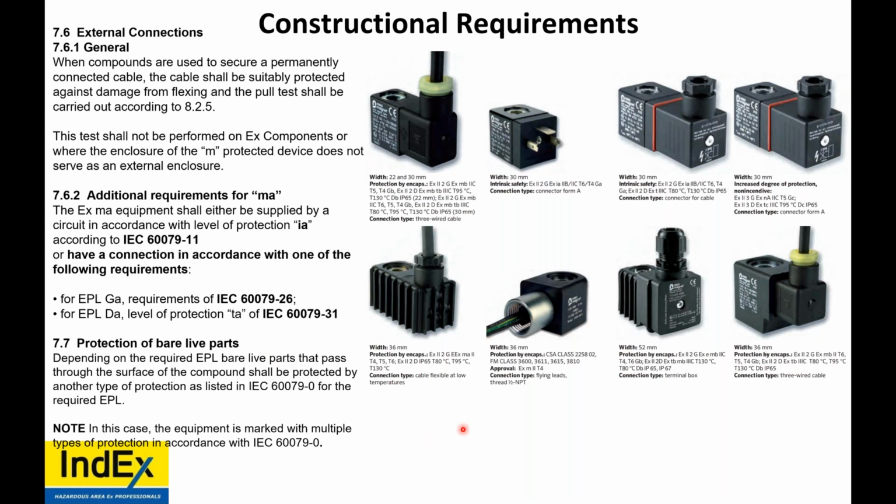Now, protection of live bare parts, depending on the EPL: the live parts where they pass through the surface of the compound shall be protected by another means of protection. So with these devices, the terminations are made inside of the EX m. The enclosure is EX m. It is not another protection technique, but it can go in a zone 0 if it's protected by a barrier, EX i.